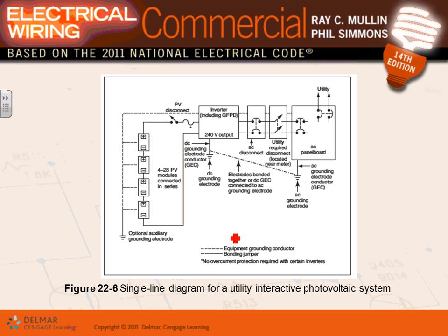They also have an equipment grounding conductor, typically number 6 copper, that you use to ground the inverter and the panels, going all the way. I want to bring to your attention, guys, in terms of sizing, the wires here as well as the fuse here: you size it at 1.56 times I short circuit for the panels, as well as the disconnect, as a matter of fact.